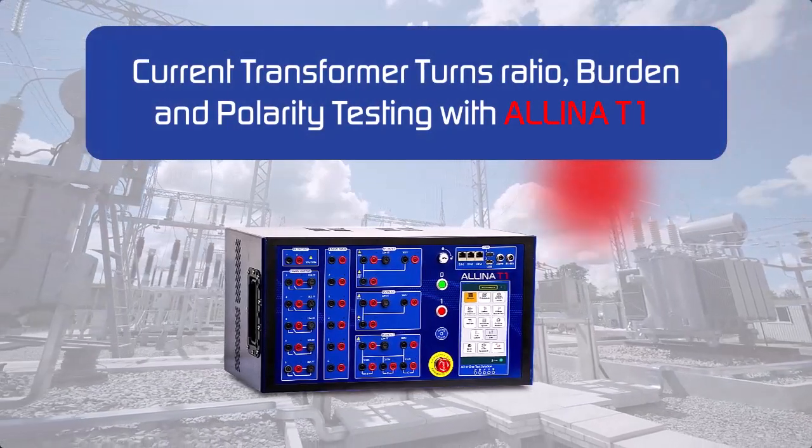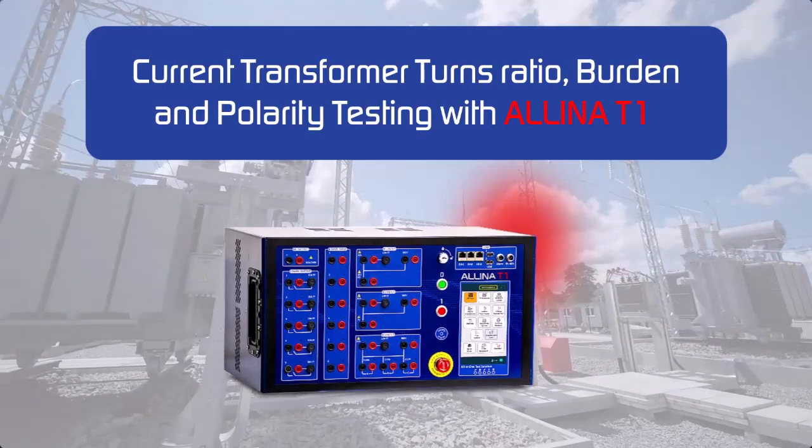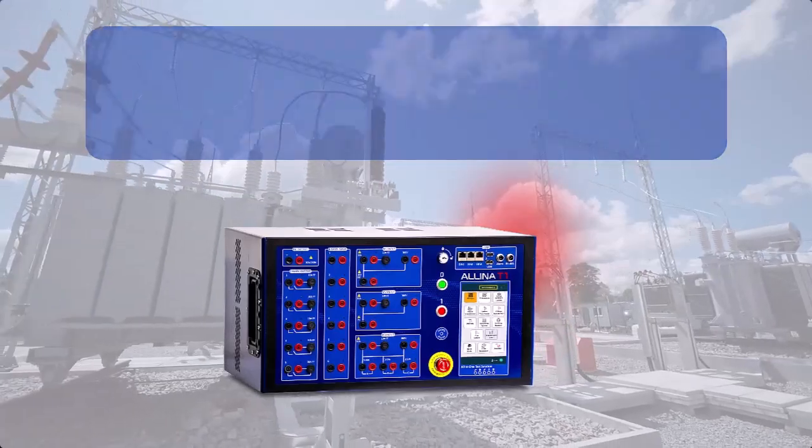In this video, we will guide you how to conduct turns ratio, magnitude and phase angle error, burden, and polarity tests by injecting current into the primary of the current transformer. Let's walk through the steps together.